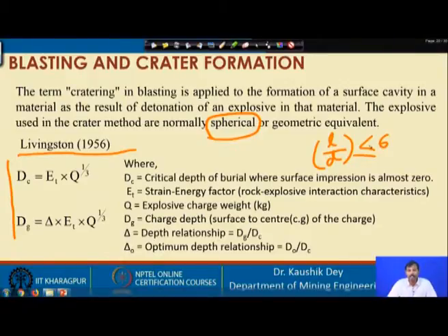That means, if the charge length being utilized for the crater experiment is less than 6 times the diameter, then the charge is considered a spherical charge. So, in crater blasting, the charge must always be a spherical charge, otherwise the Livingstone theory may not be applicable. So, with this spherical charge, Livingstone has found that the critical depth of burial, DC, can be considered